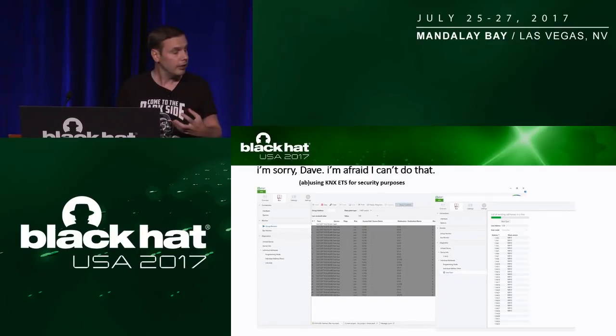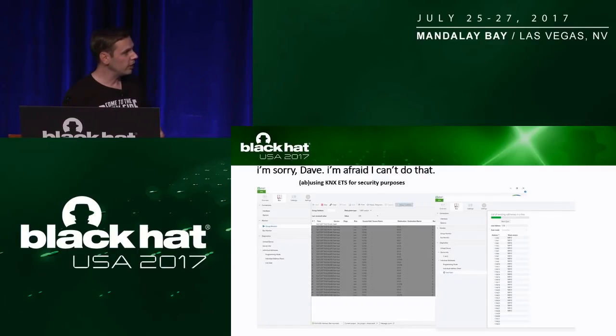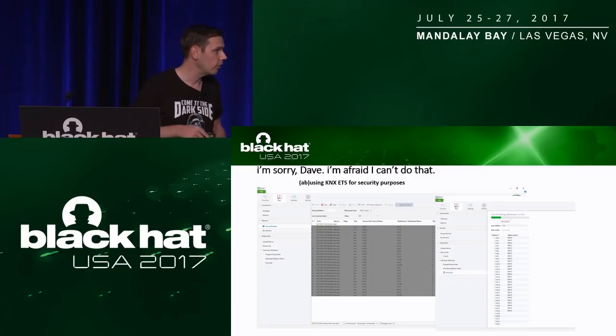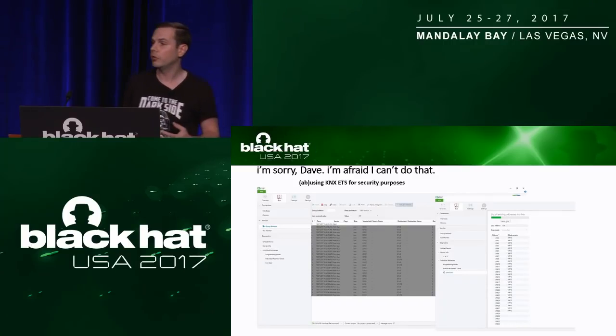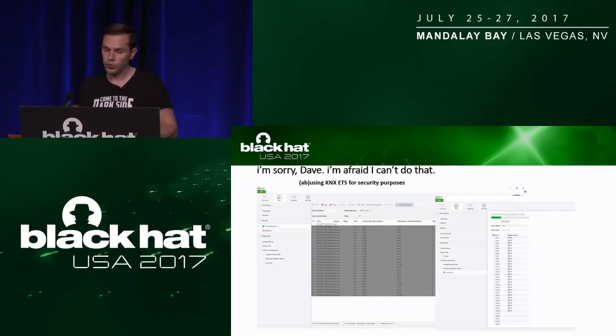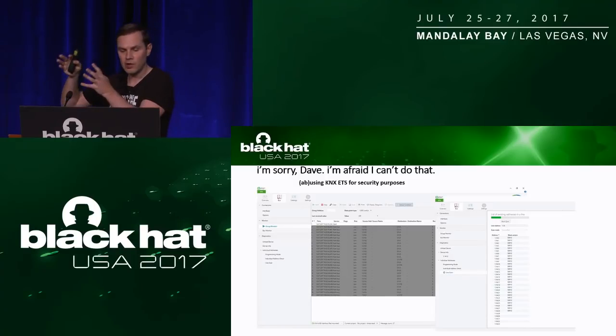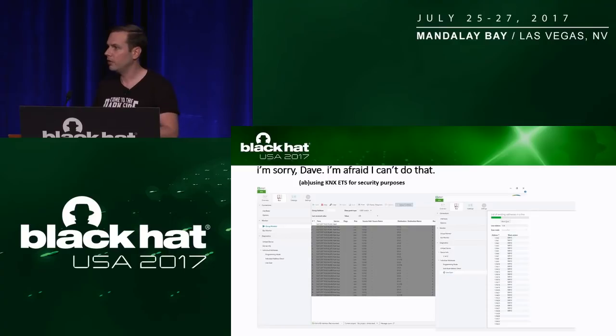So this functionality is good for passive information gathering. There's also an equivalent for active information gathering. You have that on the right side. Here I'm doing a so-called line scan, which allows you to scan specific KNX IP addresses. So you could say it's the equivalent of scanning a Class C network, but within KNX, to find out which addresses are actually being used within the system.